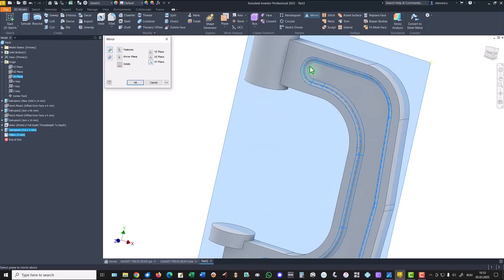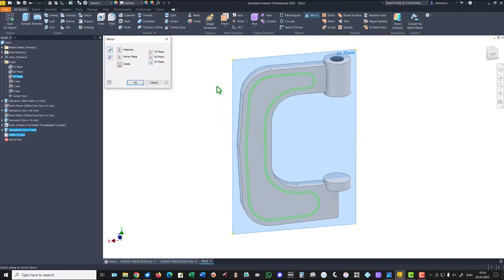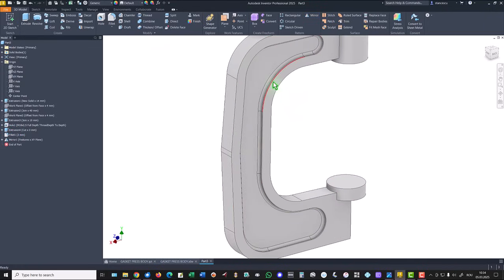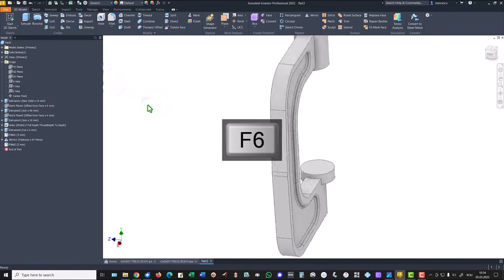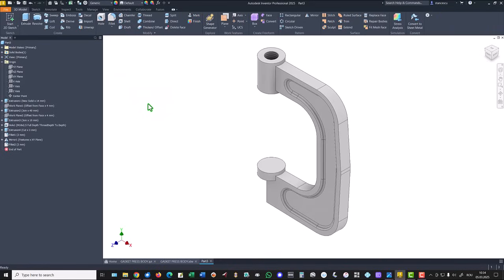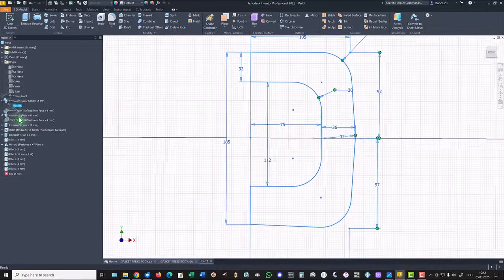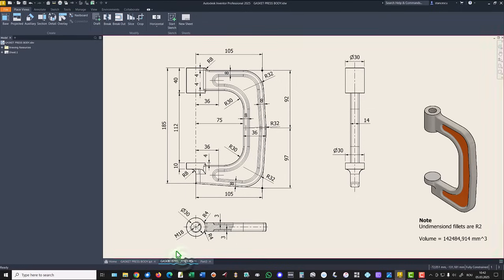You see, I place here 2 fillets and here we see only one. I don't know why this situation, so I apply manually 2 millimeters. Now I noticed that there is a wrong dimension in the first sketch. You see here the dimension of 185, and in the drawing 185 is from here.